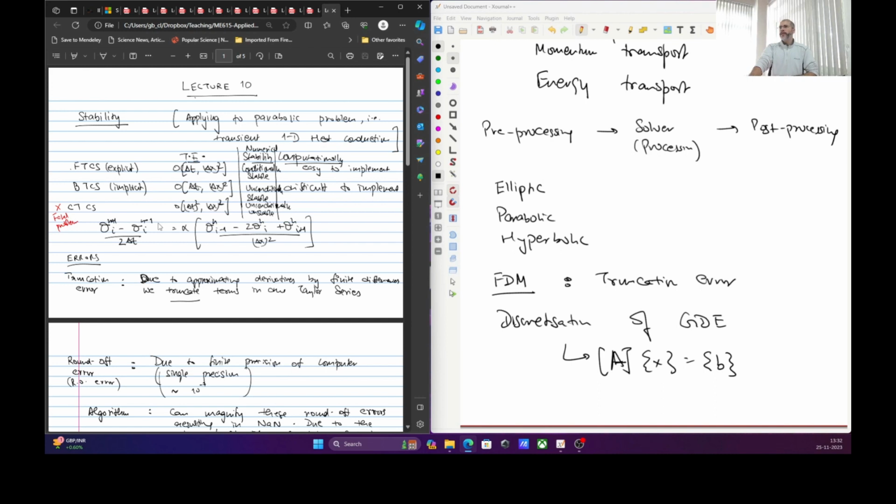So if you want to control the mesh size, you have a particular spatial accuracy requirement that results in a very stringent delta t. So if you want to move to a certain time, then you have to keep very small time steps. So lots of time steps will be required. That may result in you reaching that particular time after a few days or after a few months sometimes.